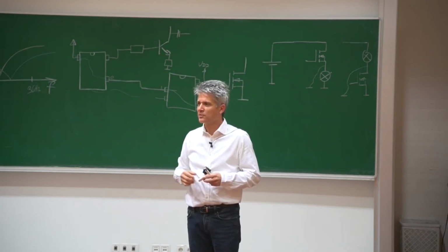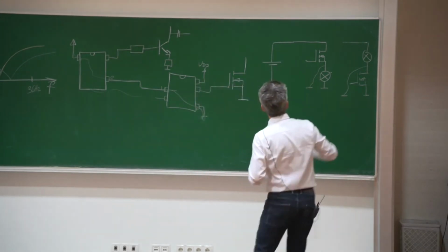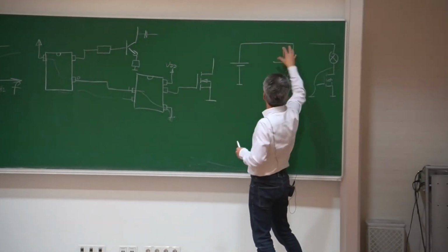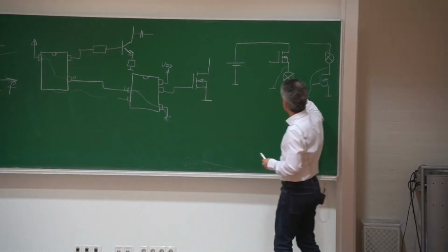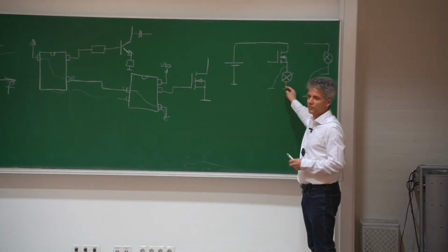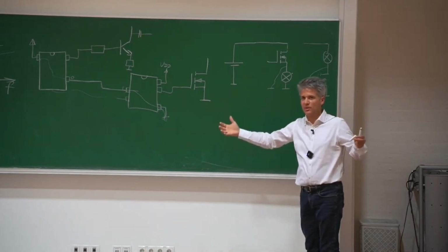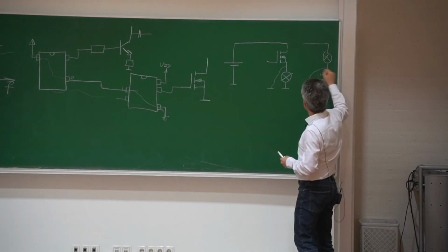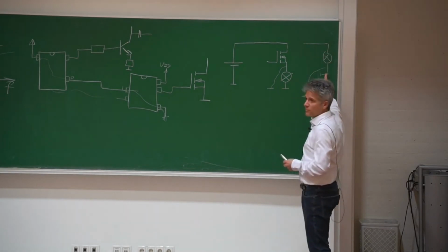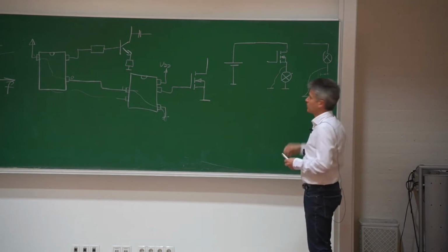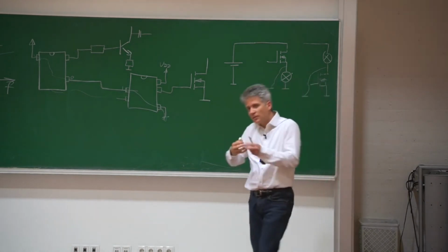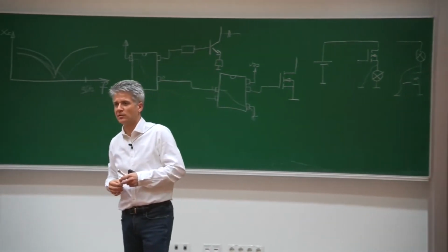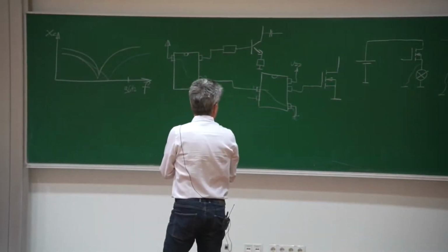But also the cable harness is an important point, because I just need this cable here. I need a power supply cable to my control module, and I just need this cable here to my load, and the load can then be directly connected to the chassis, which is usually the metal frame, the metal housing. So I do not need an additional cable here. Here I need a cable to connect the load, and then from the load I need a cable to the control module, and the control module is then grounded. And cable is weight. So nobody wants to have additional weight in a car. So these are the advantages and drawbacks.